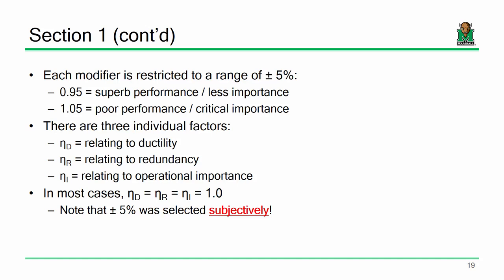It might be the most economical one, but I can tell you any bridge engineer, any DOH employee will tell you why you'll never see a 2 girder bridge erected here in the United States, and that's because that bridge will be designated as something called fracture critical. Anybody at the DOH knows that term. And when bridge engineers or bridge inspectors hear that term fracture critical, they start to twitch a little bit, and they go, oh no, let's not do that. The term fracture critical comes from the idea of a bridge that's non-redundant.